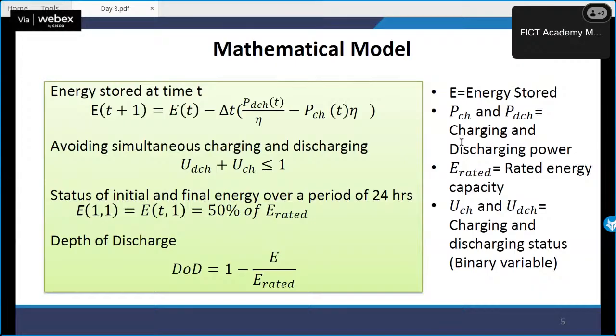At the time of charging, the amount of power being received is multiplied by an element which is less than 1. Let's say it is operating with 90% efficiency. So then 0.9 of the P that you have obtained will be stored in my battery.